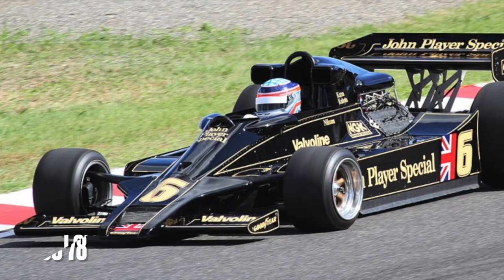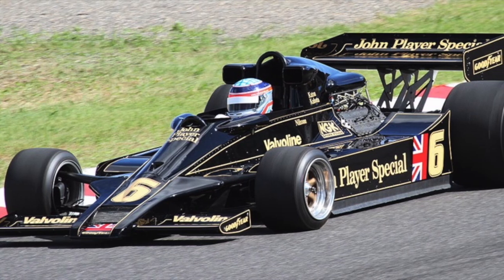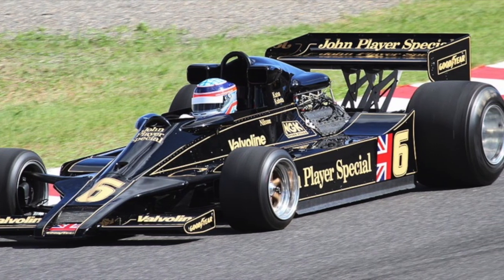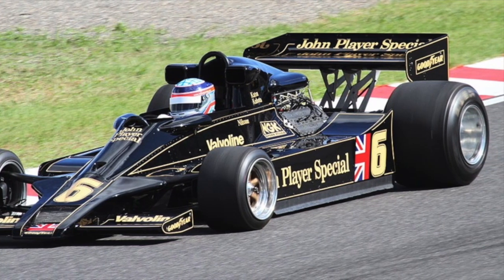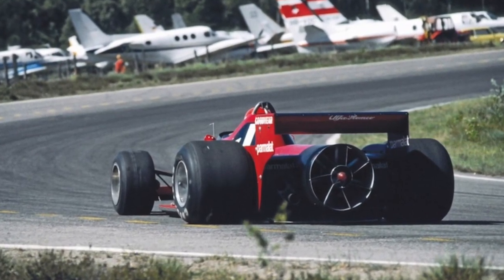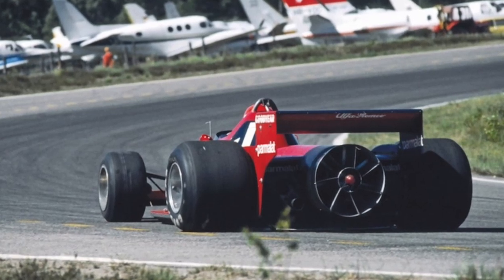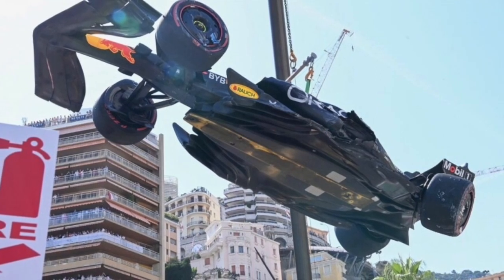The most notable example of ground effect evolution also came from the Lotus team. The Lotus 78, with its wide, low-slung body and side skirts, effectively sealed off the underbody, allowing it to generate significant grip. Additionally, other original ideas included using a fan to suck the air from behind the car, as the Brabham team did during this period. Eventually, the FIA banned most of these techniques due to safety reasons.